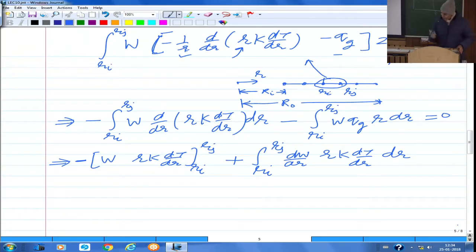Now I remember one of my friends at IIT Kanpur. One day he called me. He was working on a circular plate and doing some approximate analytical solution. In that process, some of the terms have 1 by r, and he has some r somewhere in the approximation function, so they get cancelled out. But he has some term which does not get cancelled out, so when he tries to do the integration, it goes to infinity. That is the kind of problem you sometimes have to handle. Of course, the option there was to appropriately modify the approximation functions.